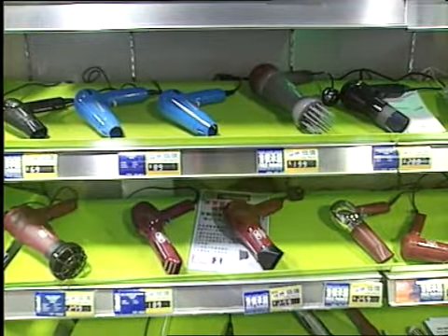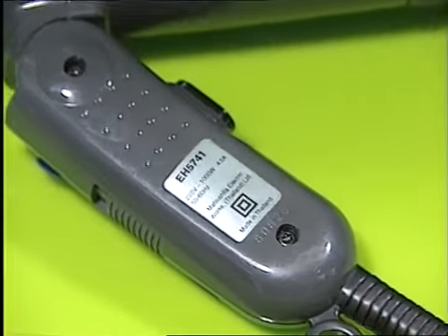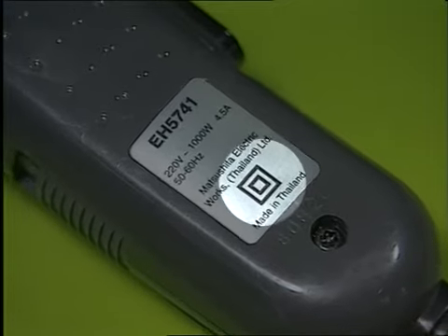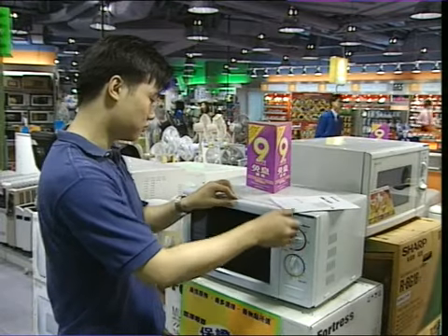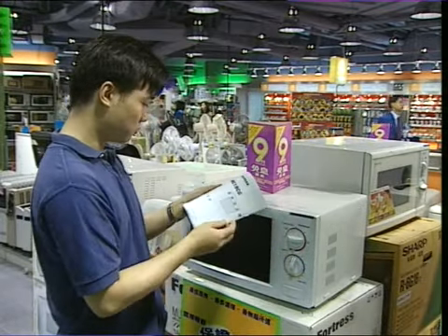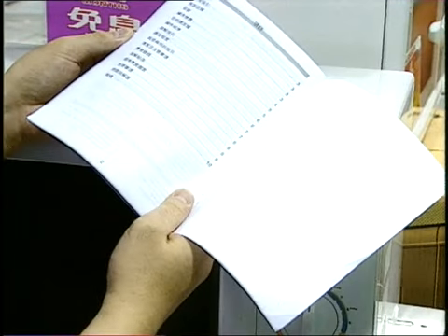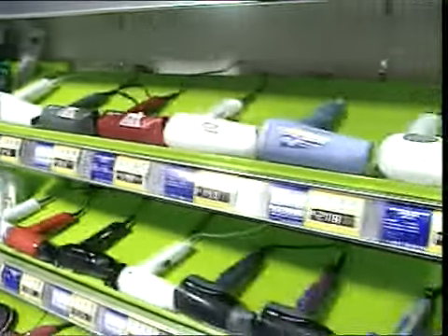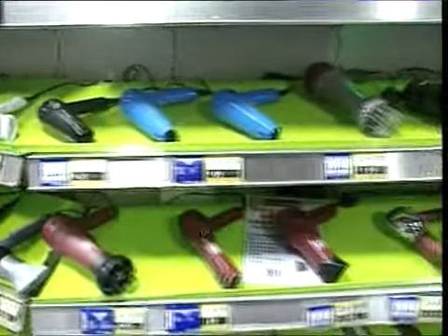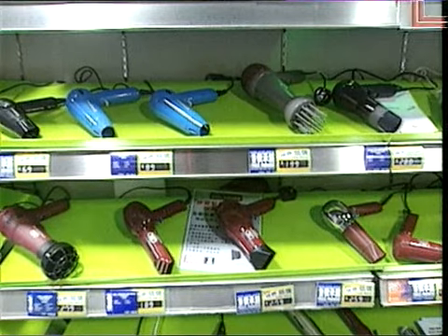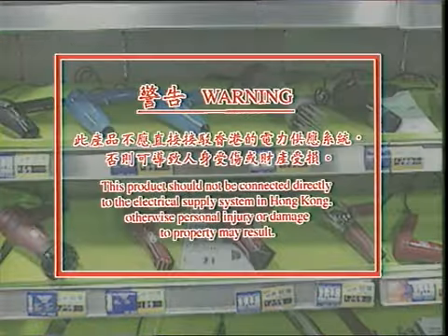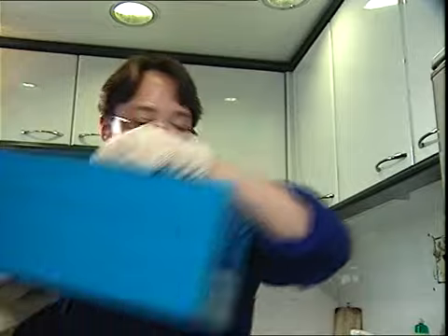Appliances with double insulating design usually have this sign marked on the casing. An electrical appliance should be accompanied by a suitable operation manual. An appropriate warning must be given if there are special operational requirements. Appliances of 110 volts should not be connected to a local power supply. A warning label against this hazard should be attached.